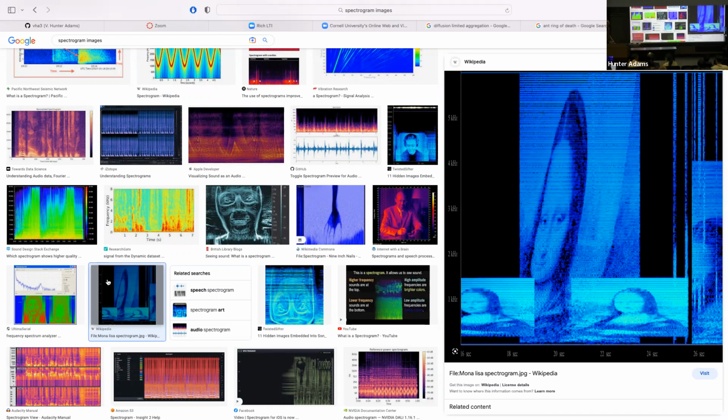It'd be pretty wild. You could do those oscilloscope images that I was talking about previously. So do a Fourier decomposition of a 2D collection of points, describe a trajectory through those points, and then generate a bunch of DDS synthesizers that will approximate that trajectory in the 2D plane to generate an image on the oscilloscope and an associated sound. Or alternatively, drop the fundamental frequency of those direct digital synthesizers from something that's audible to something within the realm of possibility for, say, a stepper motor, and draw the pictures on an Etch A Sketch by driving stepper motors to turn the knobs. That'd be pretty neat.